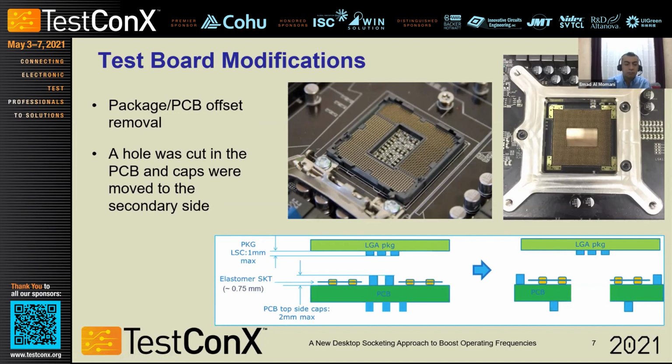Easier to shorten the PCB trace instead? That's right. No, I think the trace length will depend on where the DIMM cards are located versus the CPU mainly. So I expect it to be longer than the bin height of 3mm. Yeah, there is always a strive to move those cards closer and closer to the CPU, but that also faces some other challenges from mechanical and other aspects. So I hope this answered the question.